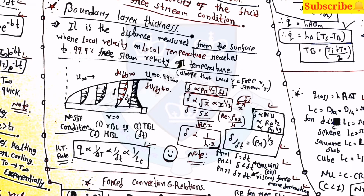Here in general you have to remember that Q is proportional to 1 upon delta T, 1 upon delta, and 1 upon Lc. This note is most important in the examination because questions are frequently asked based on the relation between delta and delta T. So for Pr equal to 1, which is the Prandtl number, delta is equal to delta T. For Pr less than 1, delta is less than delta T, and for Pr greater than 1, delta is greater than delta T. So in general you can remember that Pr is proportional to delta.